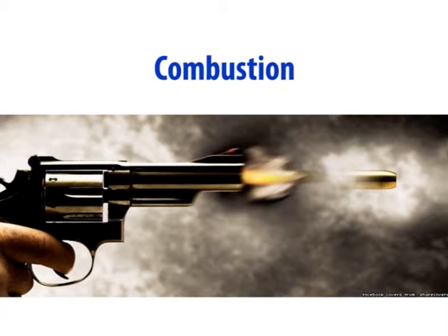It takes place when the reaction of the burning propellant or substance arises out of its contact with the air in an open space. If the reaction takes place in an enclosed space, this space should be large enough for the heat generated to be dissipated and the gases produced will disperse without generating any significant increase in the pressure. The spreading of fire is brought out by the gradual heating of the surrounding area.